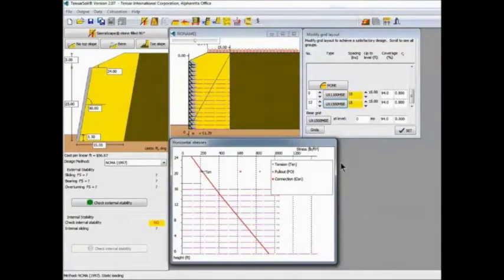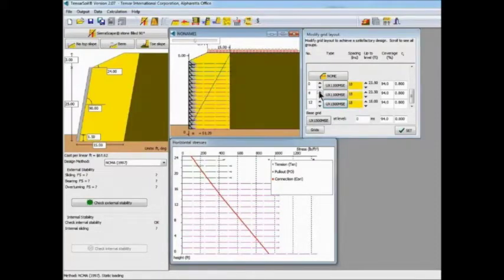and it will automatically utilize the geogrid layout that we last used for the MESA system as best as the program can make it fit. So instead of 24-inch spacing, we are at 18-inch spacing. And now let's add some layers of geogrid to get to the top of the wall. And you can see that the geometry has all been maintained, the loading conditions have been maintained, and the geogrid is now over-designed. Again, we went from 24-inch spacing down to 18-inch spacing of UX 1500.